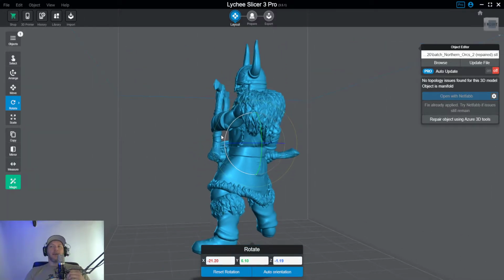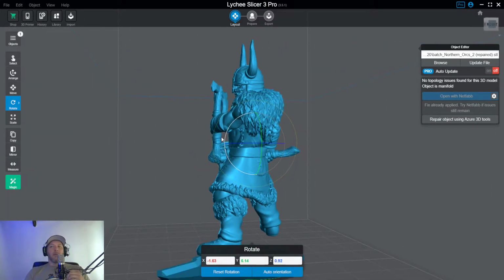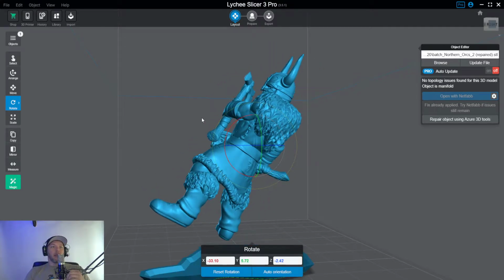If I stand it straight up perfect, maybe I have 200 supports or 200 islands, but I tilt them back a little bit, I have 155. Well, there we go, right? I was able to maintain all the priorities in the priority list, but I was also able to save myself a little time and have less impact on the model. So just a couple of things to consider.